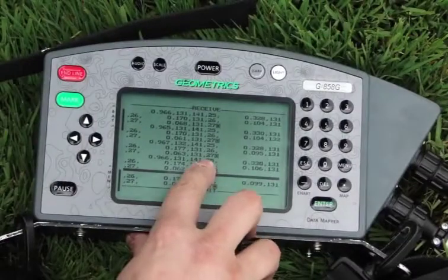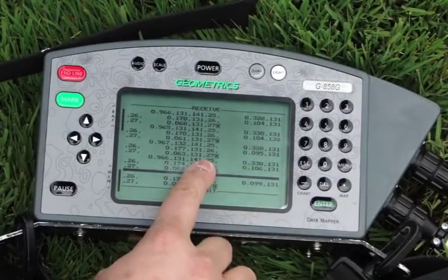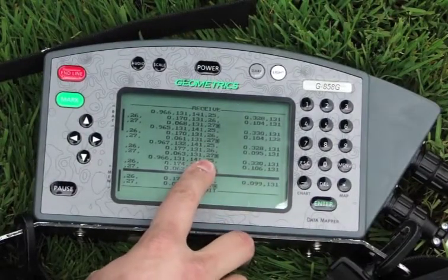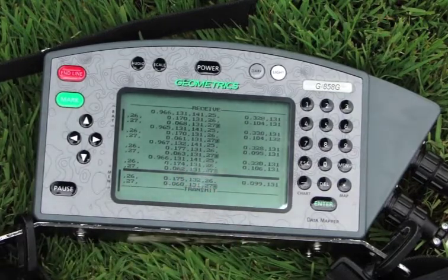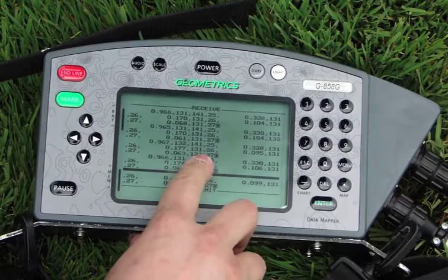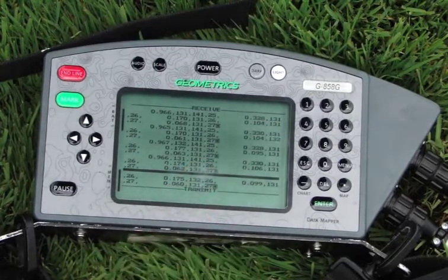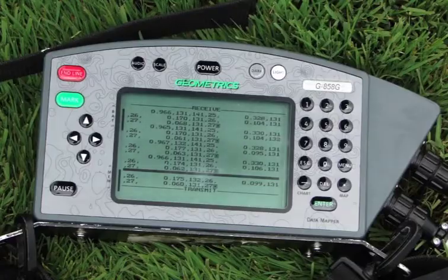Once again, the fourth set of numbers here, the first digit of that corresponds to the current level from the transmitter. In this case, it says 2. That number should match the code that's being flashed from the LED on the transmitter. And so that number, in this case 2, should match the code flashed from the transmitter.